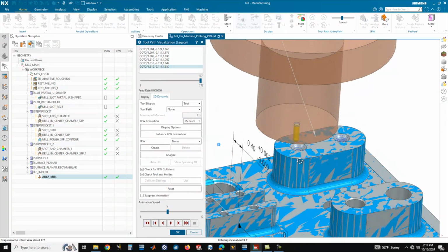And that looks perfect. Here we can really see the power of Siemens NX CAM. Not only are we able to create a CAM template that contains our roughing operations that remove the majority of the material that we need to remove off the part, but we can use the out-of-the-box feature-based machining to recognize parametric features.